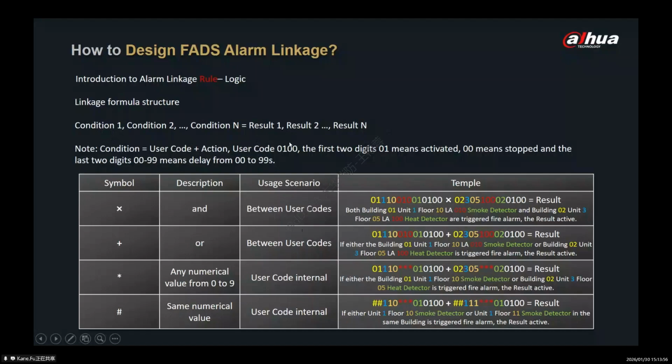For example, the default is 0100. The 01 means active, 00 means stop. And the last two digits are the delay time from 00 to 99 seconds.